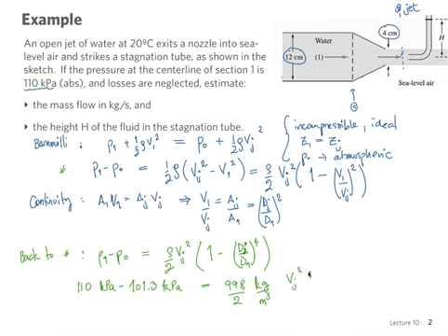Vj squared, 1 minus, and the diameters. Now it doesn't really matter what units I have the diameters in. I don't have to make conversions because, since I have a ratio, it's always going to be dimensionless. So I can just write 4 over 12 here, because any conversion to meters would cancel out. I just make my life easier and write 4 over 12 in centimeters. The units cancel out, and this is to the 4th power, the diameters.